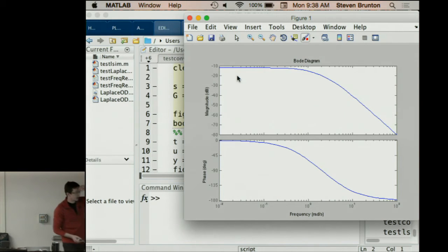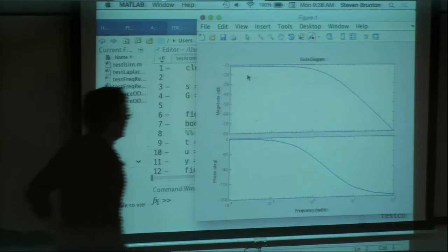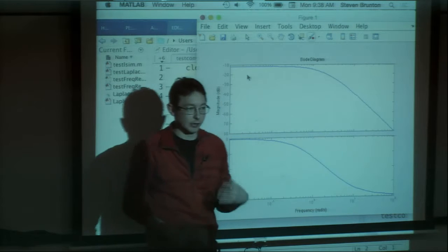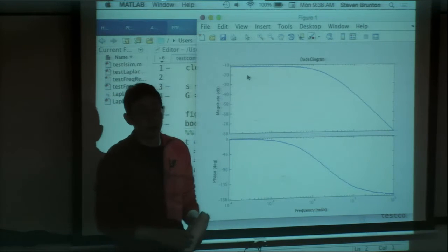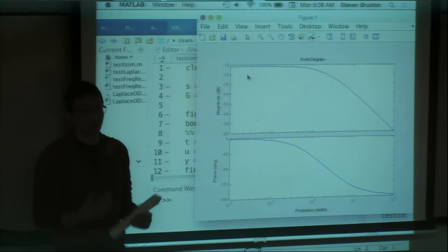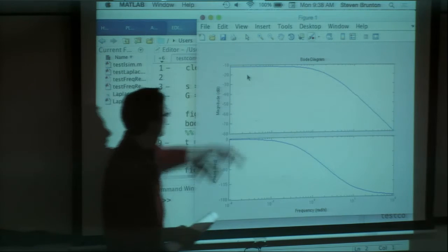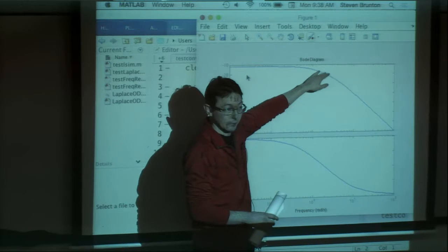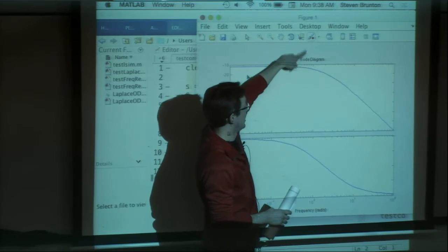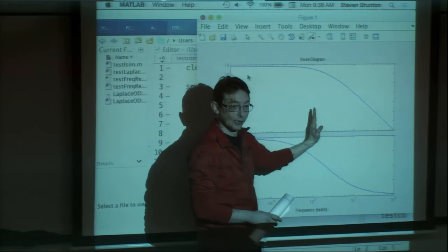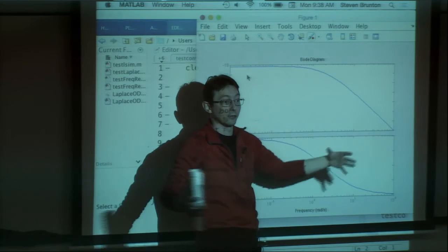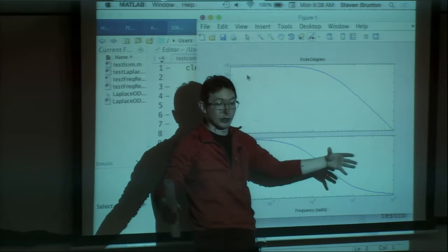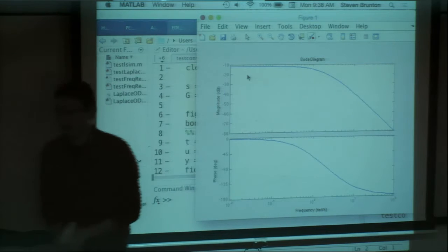This is a really important thing in control systems and in mechanics and vibrations and materials if you want to know where your system might be sensitive to instability or resonances. Because if you see a sharp peak anywhere in this Bode diagram or this frequency response, that tells you that there's some input frequency where if I force my system, I get a lot of response out. I might even get an amplification in the response. And that could cause system fatigue.